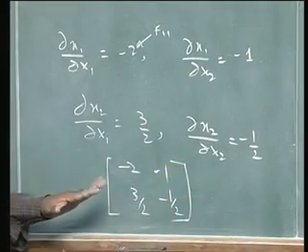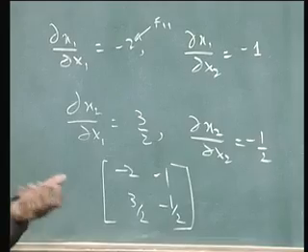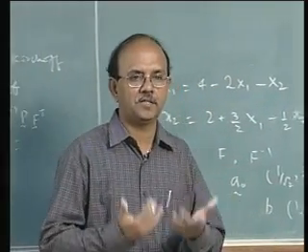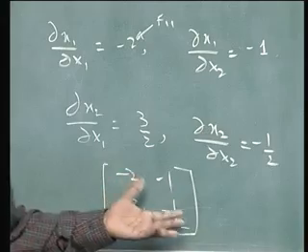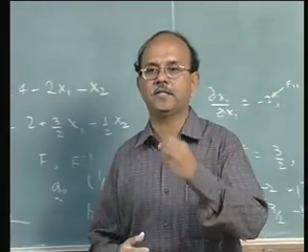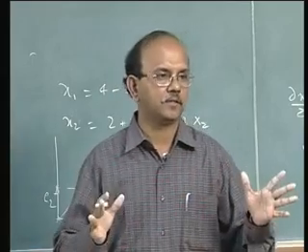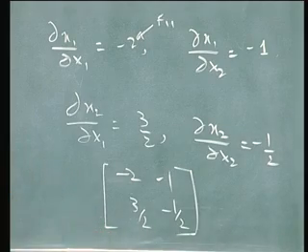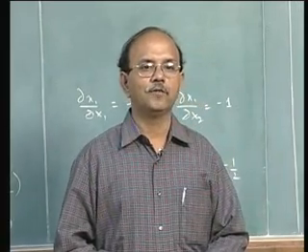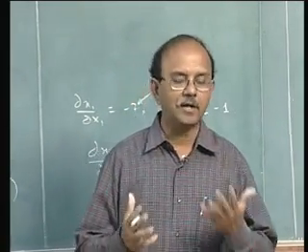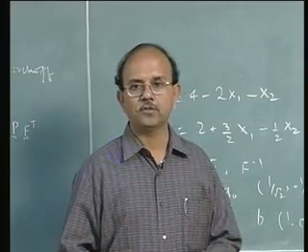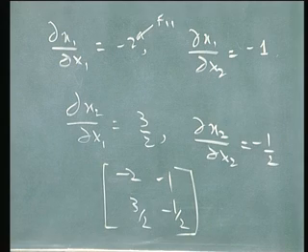The first thing I want you to look at is it is not symmetric. Unfortunately, I have seen over the years many students making the mistake of assuming that F is equal to F transpose. They are so used to symmetric matrices in their earlier mechanics and structural mechanics courses. K is symmetric, sigma is symmetric, epsilon is symmetric. So they think that every matrix that comes in continuum mechanics is symmetric. Be very careful, because many formulations in nonlinear analysis will land you up in unsymmetric matrices. They have their own problems. The storage is going to be high, the time required to solve them is going to be high, and so on. So please note that. Now calculate the F inverse for this.